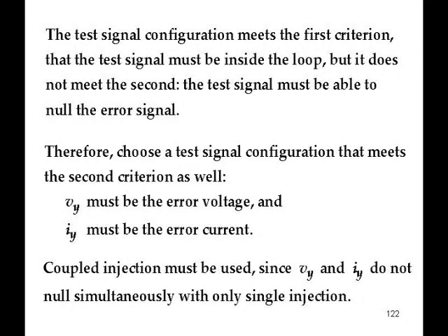So this was an okay injection point to get the right loop gain, but it's not an okay injection point to get the right H infinity. And the Tn will be wrong as well. It has to be wrong. Because when you plug them either set into the final answer, it's got to be the same. So if the T is the same for both injection points, and the H infinity is different, then the Tn has to be different as well.